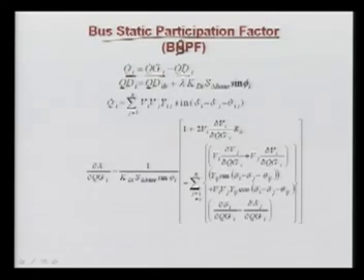This reactive power demand can be written as the reactive power demand at that bus in the base case, plus lambda, which is a loading factor. If lambda is 0, then we have the base case starting point, and here we have some factor, that is, how much change you are making in the base, and you can also have some power factor change for the real power loading.